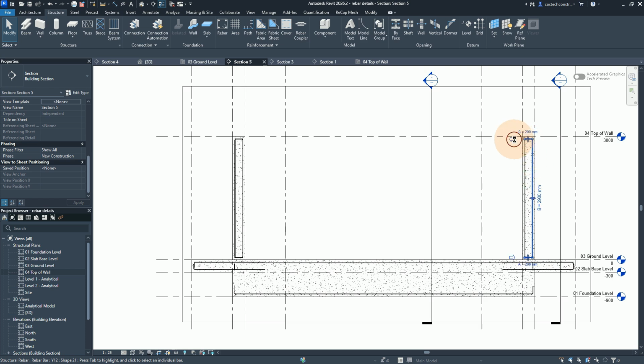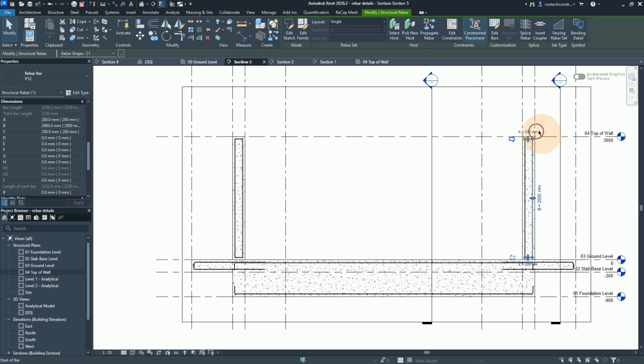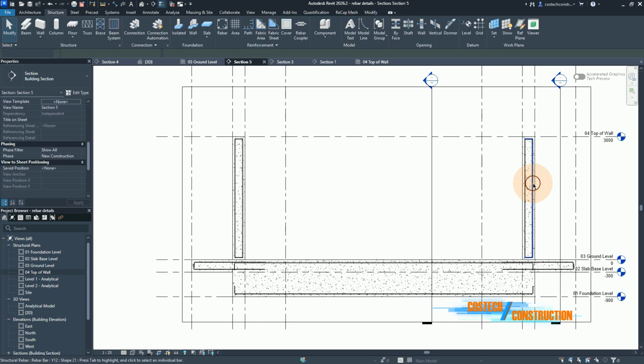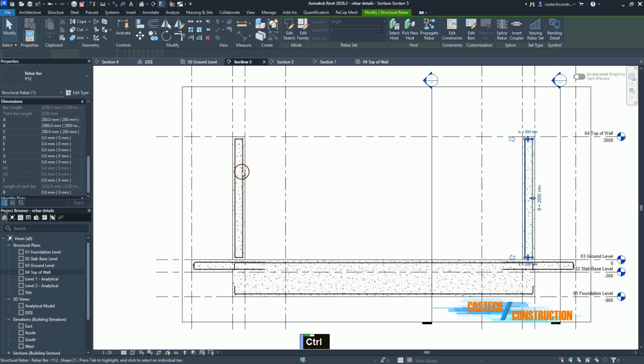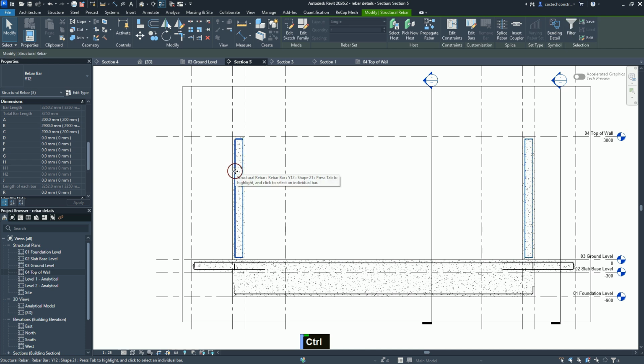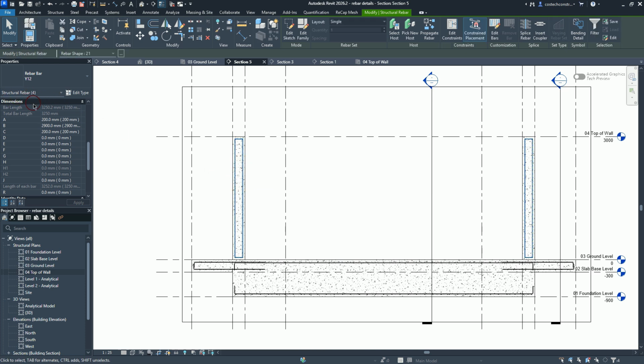I can now click here to change. Now A will be at the top. I'll press escape, and now we can select all these rebar sets, then change the value of A, B, and C at once so as to edit all of them. So I'll select this one. I'll also select this one. And you can also select this other rebar set here. Now that we have 4 rebar sets selected, you can go to the ground level.